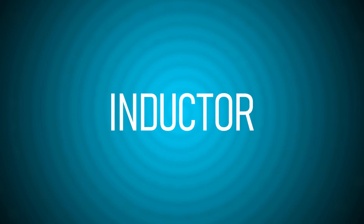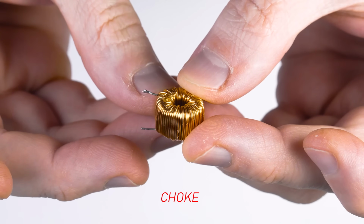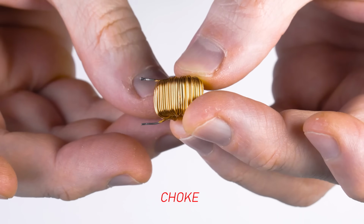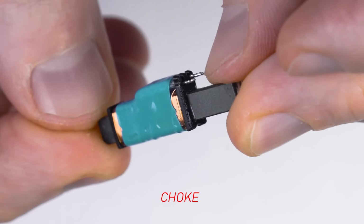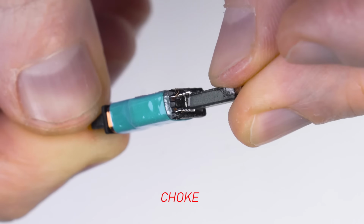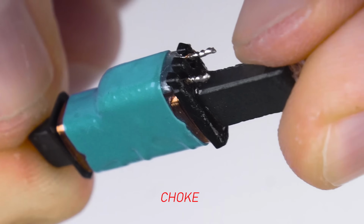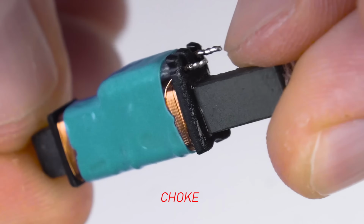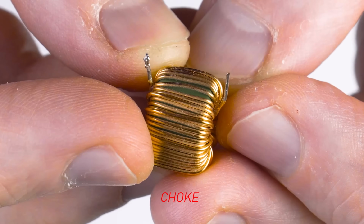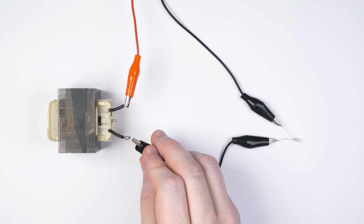The inductor, also called a choke or a reactor, is similar to the transformer by design and can also have a conventional or toroid layout. But unlike a transformer, the inductor has only one winding and only two terminals. The inductor, just like a capacitor, can store energy. However, it releases all energy immediately after the supply voltage is removed, unlike the capacitor, which can store it for a relatively long time. You can observe the operation of a choke with the help of two simple experiments.